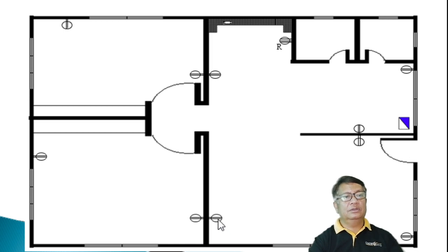If you are planning to have three convenience outlets, then it is advised here to have three parallel lines, so that we will know how many outlets there are for this specific convenience outlet. As you can see, one of our outlets here is a special type, and we use this symbol. This is used for the electric range outlet, so it is located in the kitchen area.